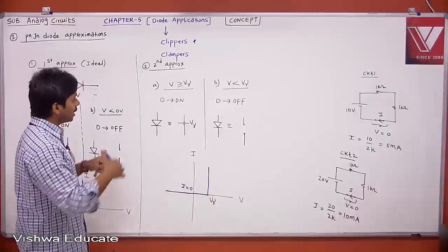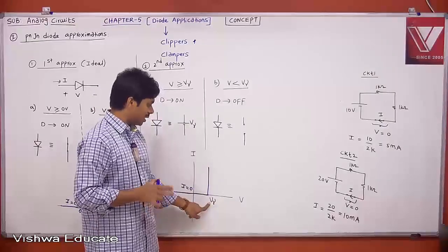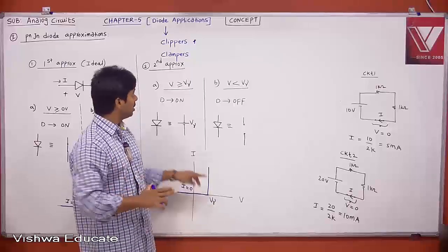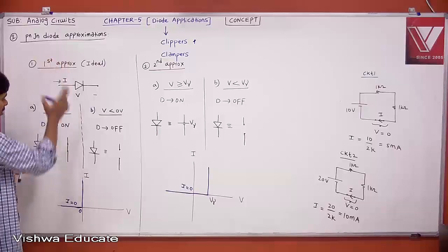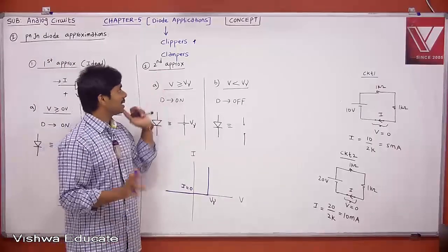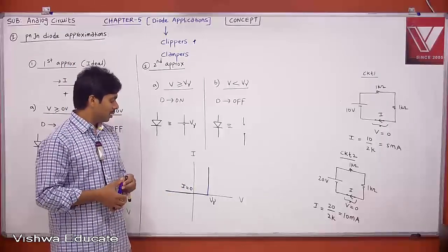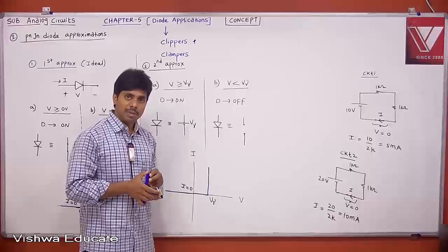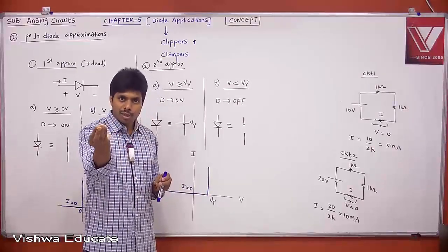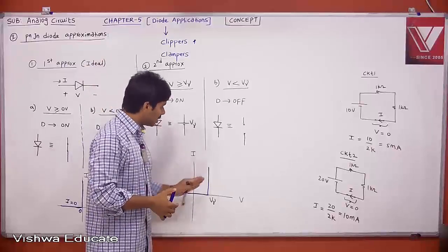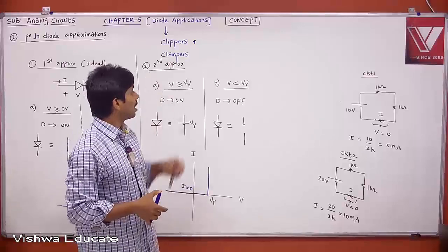Then people incorporated one more level, which is nothing but your current. The voltage across PN junction diode is V gamma, that is fine. But most of the time people took the second approximation, unless people say explicitly ideal model, which is very easy to solve problems. If people say second approximation, then we need to construct the V gamma, then after V gamma it is on only, like a battery. But we know that in a real PN junction diode, the voltage across the diode can be more than 0.7, 0.701, 0.702, and then only current will increase. Therefore, the increase in current with respect to increase in voltage above V gamma is also incorporated. That is what is the third approximation.